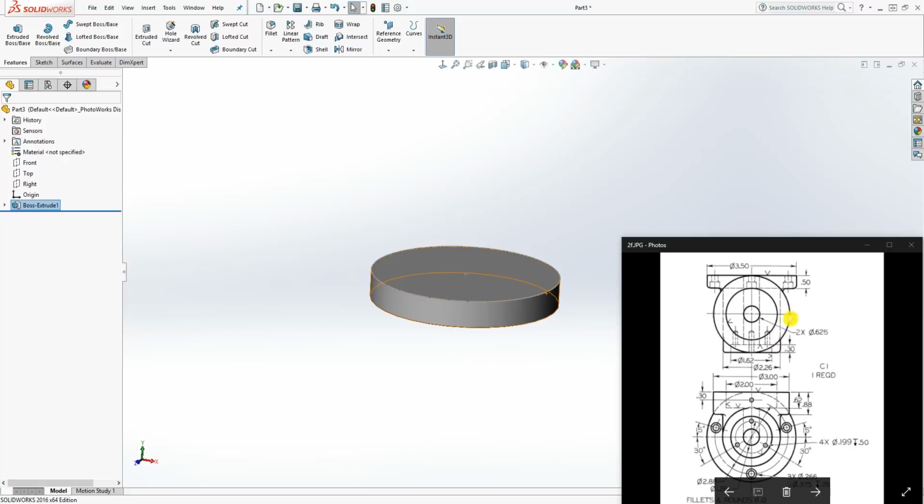If you track this circle down, that's a drafting technique, like I was saying earlier. The way I was taught is you take a ruler and just draw a line down. Whatever that touches is what you are looking for. If you track this line down and that line down, it is 3. Since that is 3, the length down will also be 3.